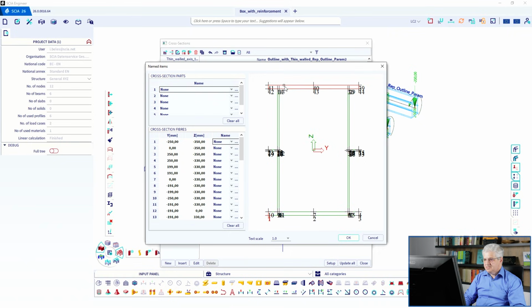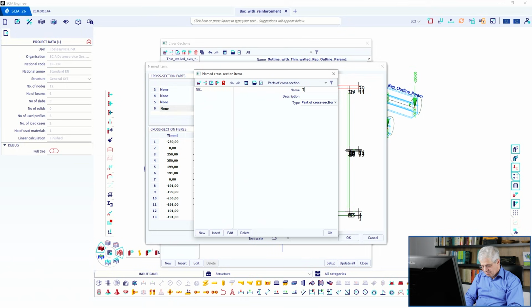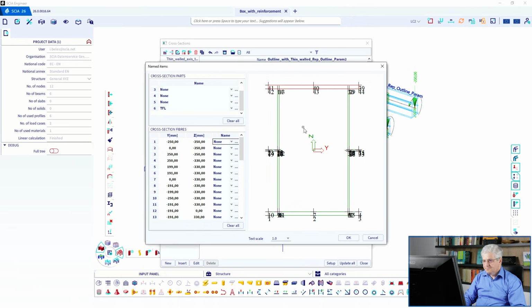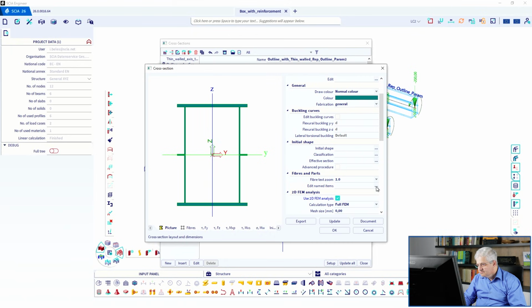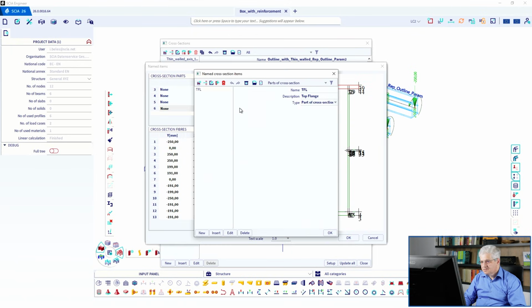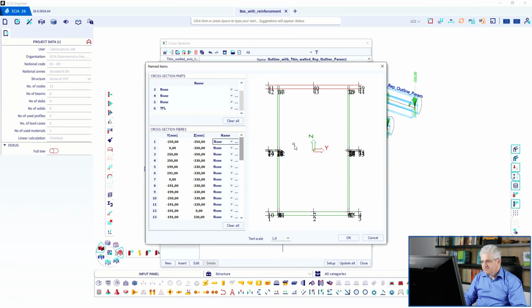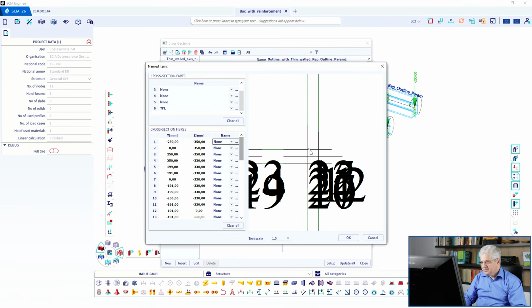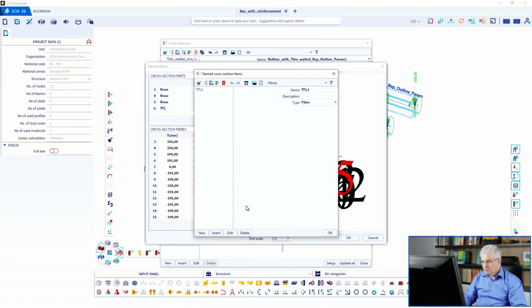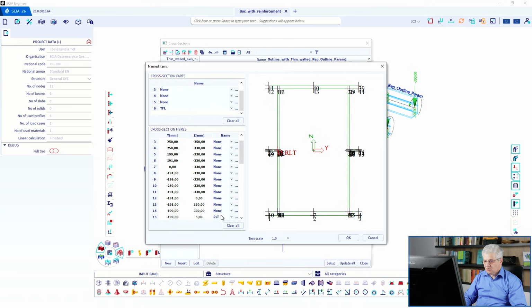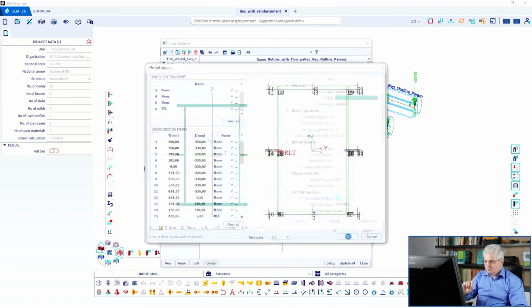And because I have inputted this part as a separate polyline, I can say this is one part with one name. Let's say top flange. So I can select it, go to this 3 point and say this is top flange. Okay. It's correctly defined. And let's say I would like to evaluate the stresses also in this point 15. And this point should get the name, let's say, reinforcement left side top point. It's a fiber. Okay, so it gets also a name. We have one part and one point with a name.